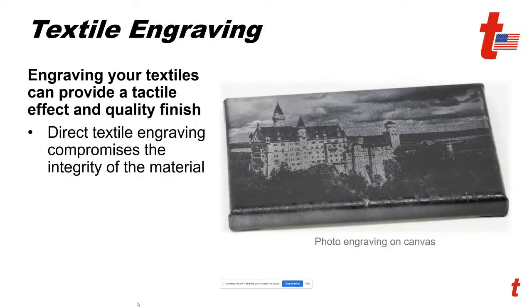Now, engraving into textiles can produce a tactile, really neat effect that can't be produced any other way. Direct textile engraving can compromise the integrity of the material, so you want to be careful. Too much power can produce a beautiful effect in the fabric. However, the problem is when you go to pull on the fabric or wash it a few times, it starts coming apart. So there is a very fine line in engraving fabric: how much depth you can engrave into it, what kind of contrast you can get, the color of the fabric, the type of the fabric.